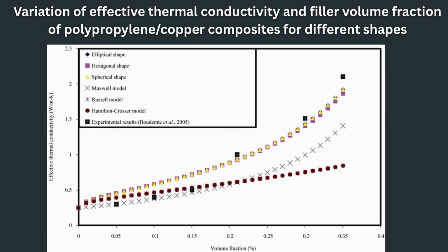Particle morphology also plays an important role. Copper flakes are more effective than spherical particles because their large surface area enables direct contact, reducing thermal contact resistance and thereby forming more efficient heat conduction pathways. Nevertheless, flake-shaped fillers also increase the viscosity of the adhesive due to greater friction between the filler and polymer matrix.